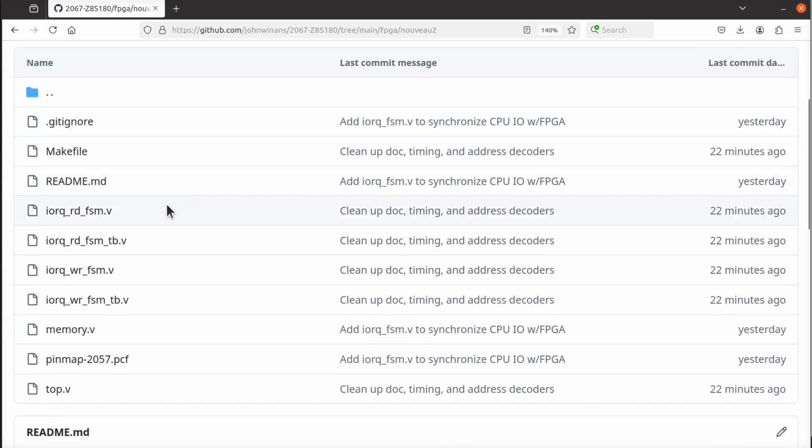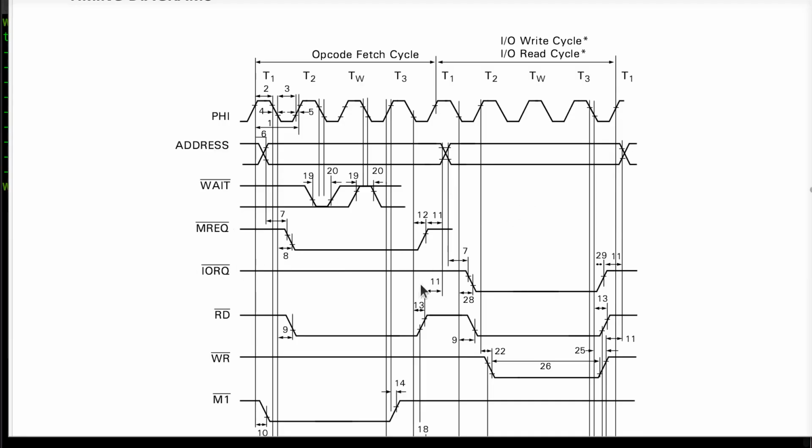I'm very specifically going to talk about the test benches and cases around these finite state machines that I'm going to use as special synchronizers that are not really metastable style synchronizers, okay? So don't confuse that. This is the whole point of today: this specialized synchronizer that I'm going to use so that the FPGA can recognize one of these edges from the phi clock that's running during an I/O operation and/or a memory operation, or a bus transaction, we should say, right?